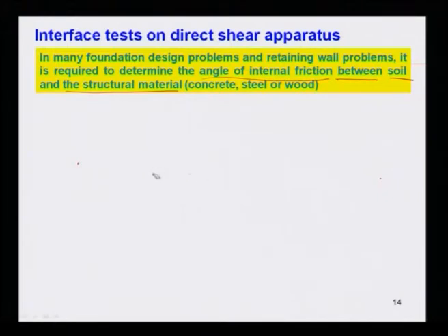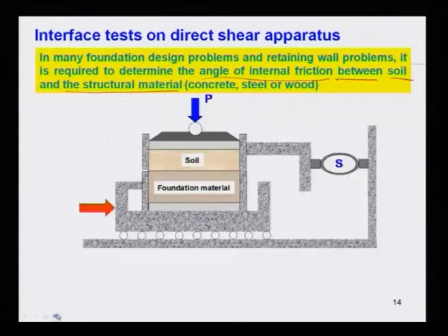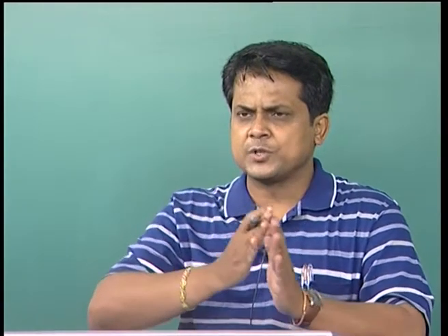Can you imagine how you are going to find it out by means of direct shear test? Just think, look at here, this is your complete test setup. In this test setup, in the shear box, what has earlier been done? Earlier, the complete shear box is filled by soil. When you apply the shear force, the shear stress will be generated along the particles of soil.